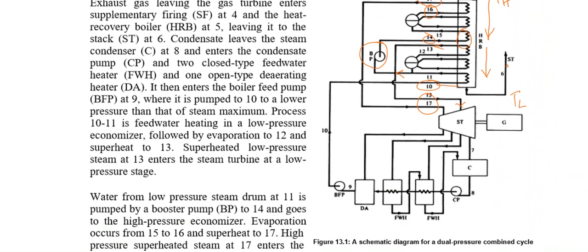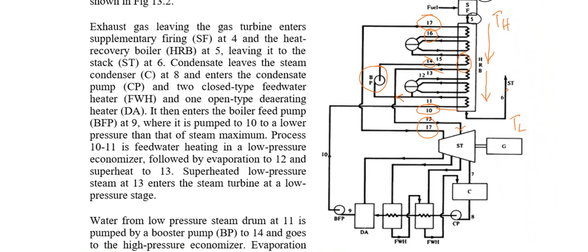So we have the energy lost by the gas cycle from 5 to 6 dash, or let's say, in total 5 to 6. In other words, if I don't have a low pressure circuit installed, I would be leaving the stack at 6 dash over here.